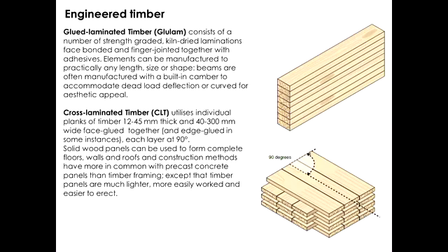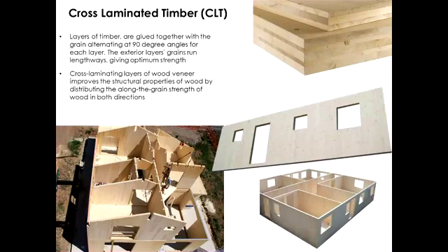To me, it's a very strong product. There are always an odd number of layers. So that means that the first and the last layers always have the same direction of the grain. Because let's say you're going to use that in this direction as a beam, you want to have the outer layers sharing the same direction of the grain. The same if you flip it and rotate it vertically and use it as a wall, you want to have the same direction of the grains. All right?